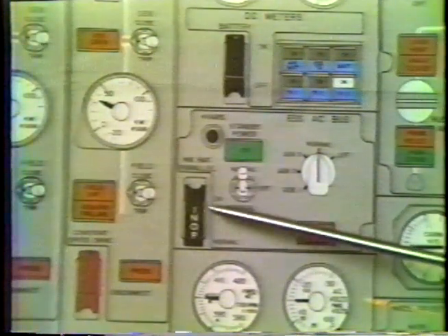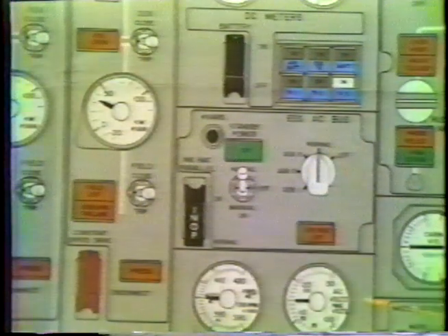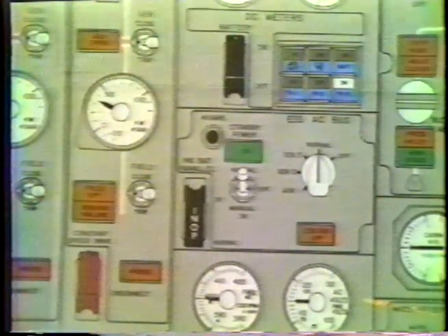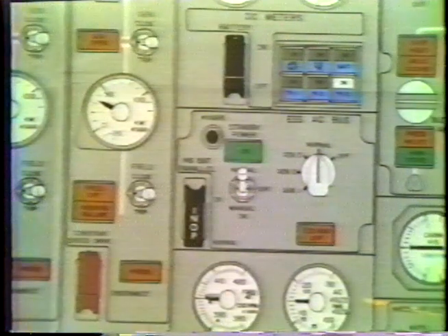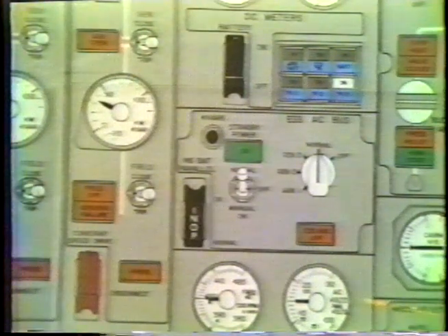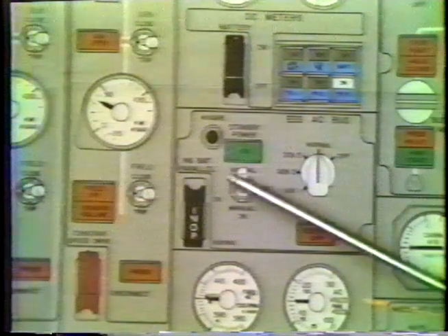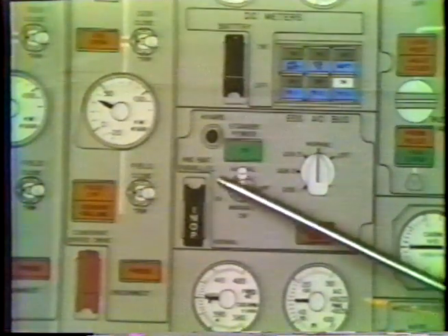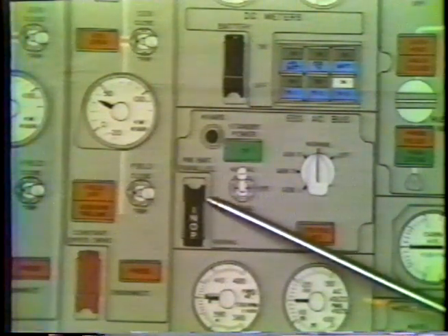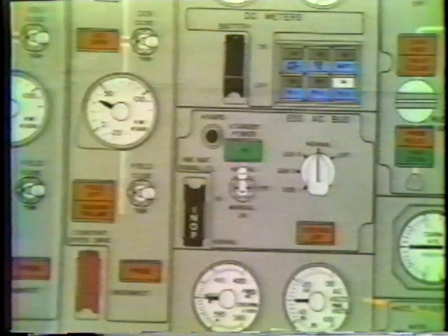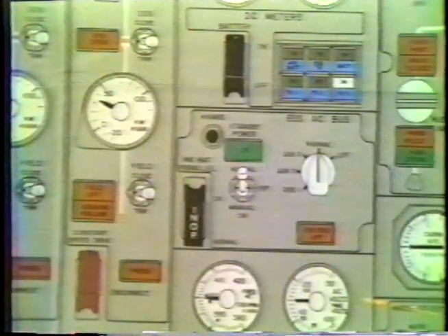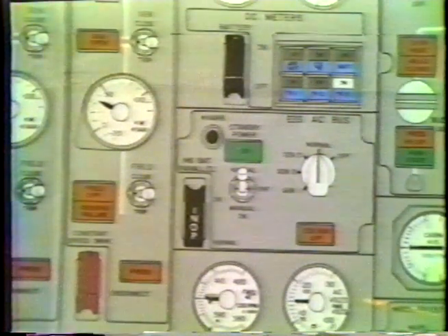Alongside the standby power switch, there's an INS battery parallel. On some aircraft which have only 2 INSs, this switch is deactivated. On aircraft with 3 INSs, it allows taking the number 3 INS battery and putting it in parallel with the number 1 INS battery to allow the number 1 to operate with loss of all generators or no power on the bus for approximately twice as long.